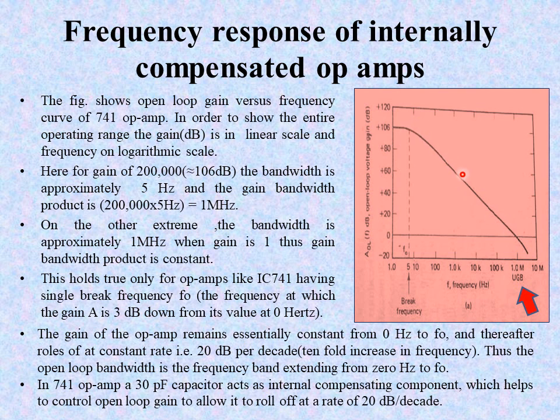So the decrease is 20 decibels per decade. That means for a 10-fold increase in frequency, the gain decreases by 20 decibels.